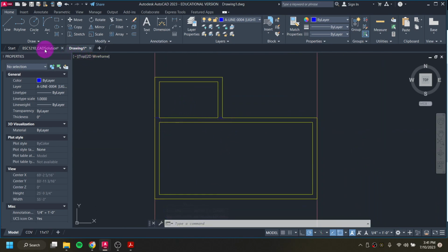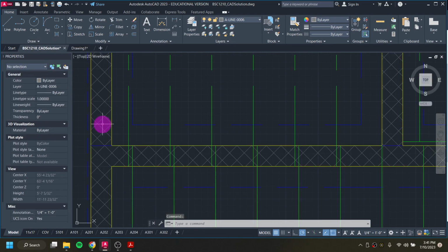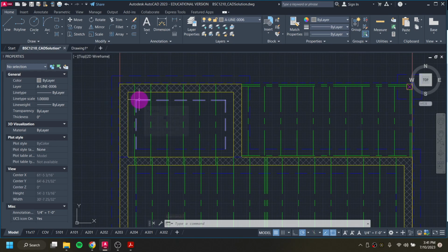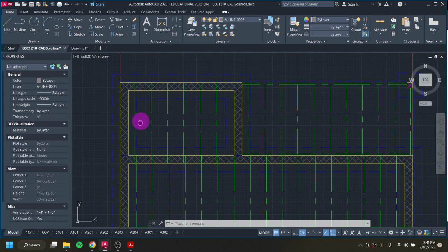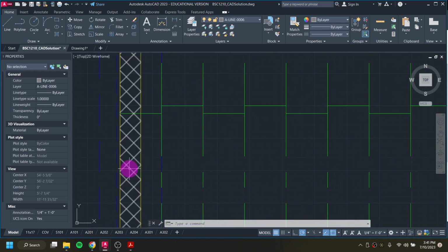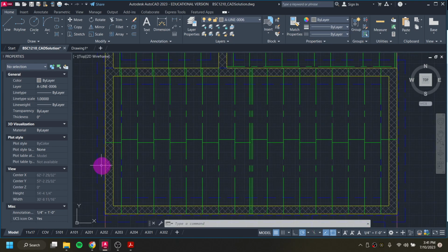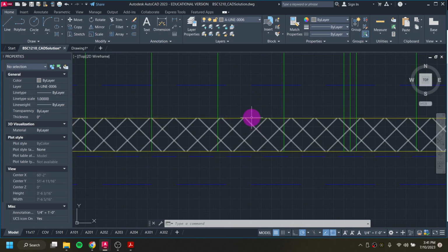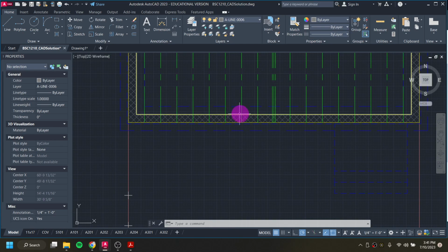Next, for our foundation, we can add in these dashed lines, which are representing our footing. And our footing is 2 foot wide in total, and it sits centered on the foundation wall. So from the center of this 8-inch foundation wall, 1 foot over is this edge of the footing, 1 foot over is this edge of the footing. It's a little easier to see if I look at it this way, purely because of the fact that this floor joist happens to sit on top of the footing.